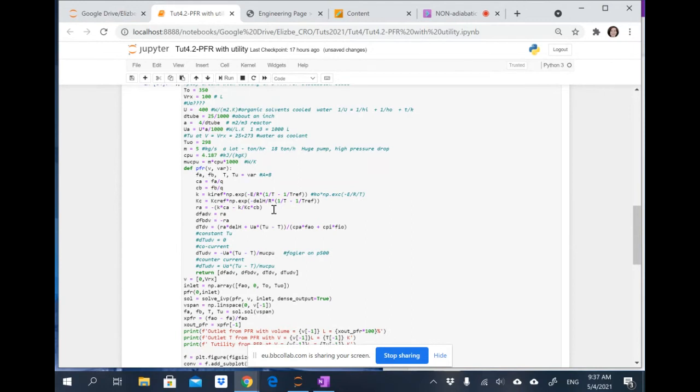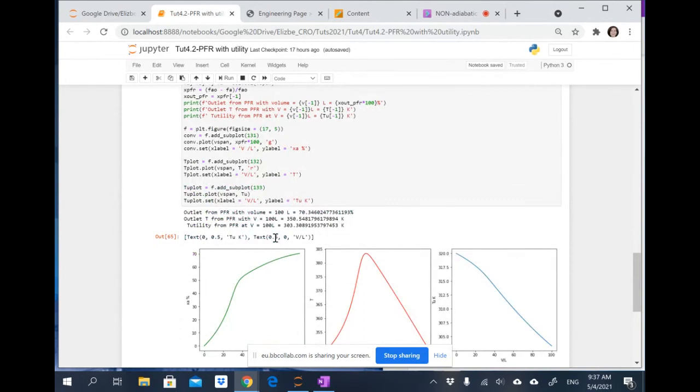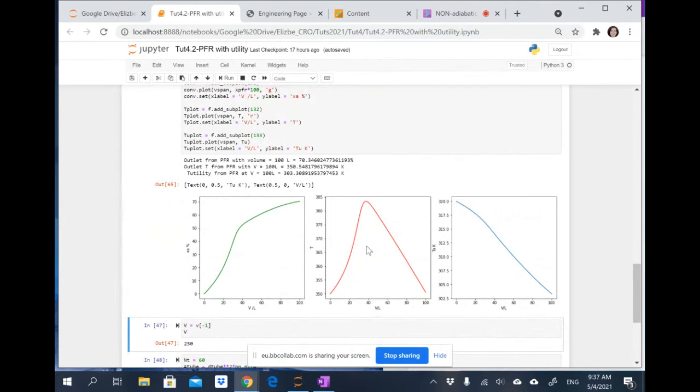So we've got the co-current now sorted and now I'm going to see whether counter current can make a difference. So counter current, there we go. And now I'm going to have to re-guess, of course, that inlet temperature of mine. So let's start at 320, still wanting it colder than that temperature. There we go. Oh, 60. So what the hell? Now we are getting some interesting profiles. Look at this. This is just by changing a button.